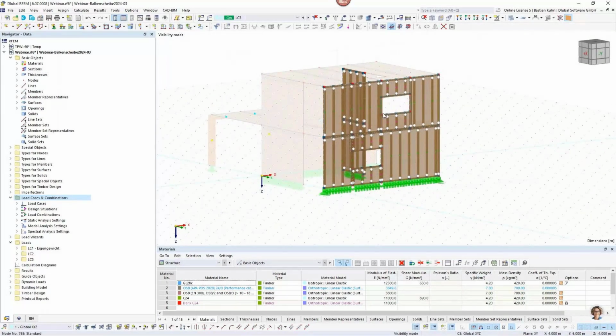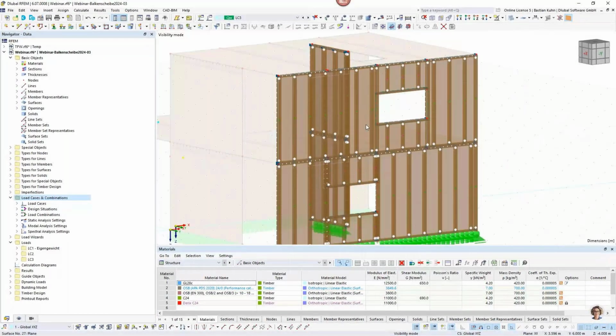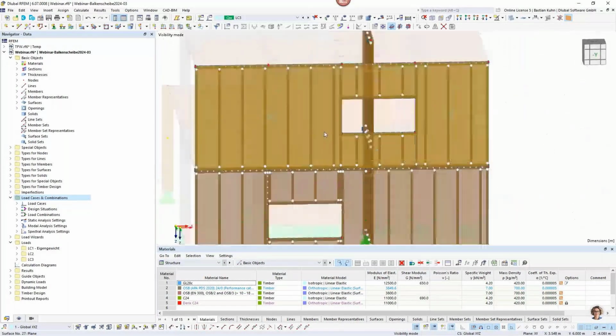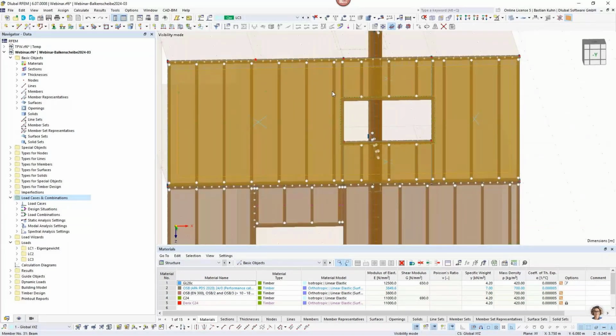But anyway, okay. So now we look at the top wall first, and we see that now the distribution of the beams and the posts is quite good. We would calculate the opening, and it kept our spacings of 625 millimeters in between, and here we have a middle value of 100 millimeter left, and this is also good because we still can get insulation into it here.